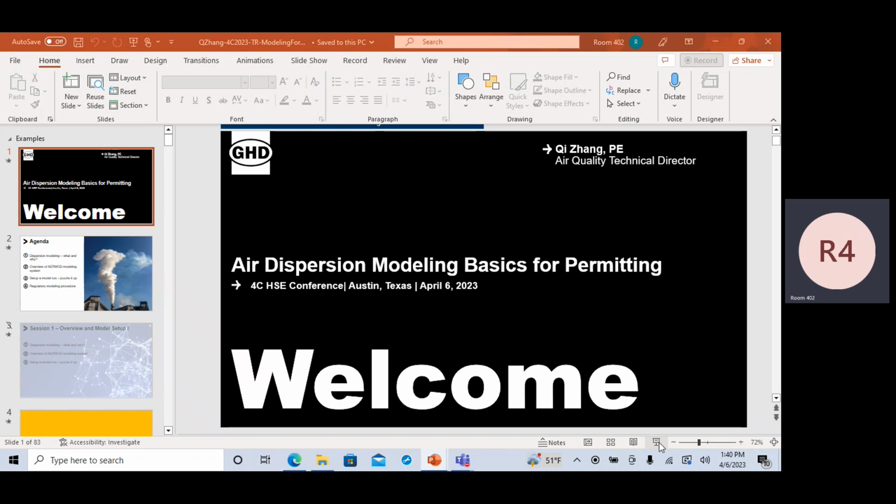Point source and some other dispersion techniques. So we talked about before, you don't want to put in more than 65 meters or the GEP height, because that's not allowed. And other dispersion techniques, you are not supposed to do something physically just to help with dispersion. So if you have a stack with a flow rate, and you modeled it and find it's not passing the model, and you think, okay, if I have a higher velocity or flow rate, it can get better dispersion.